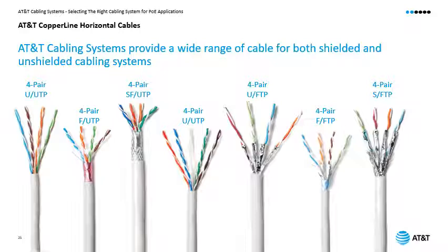All of those comply with PoE standards, and the minimum ampacity for each pair is 1 ampere, which is more than enough and suitable for all types of PoE, including PoE Type 4 as well as non-IEEE standards protocols.